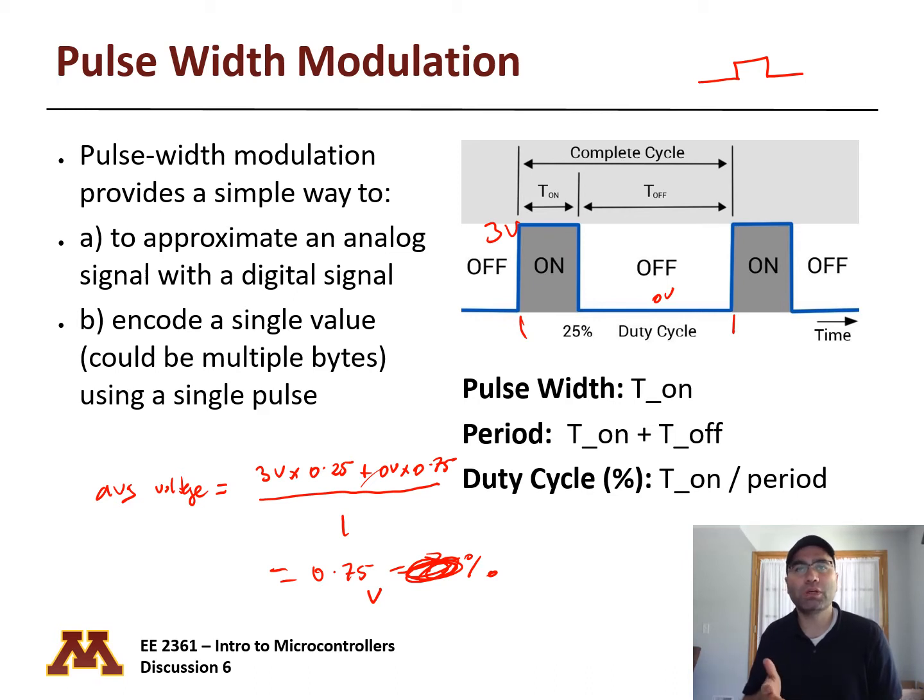This works if it is a motor, because the voltage changes very quickly. Especially with an LED and things like that, and a motor, since the digital signal is changing so fast, the motor is not going to turn on and off every time the signal goes on and off. It cannot react that fast. The same thing for an LED, right?